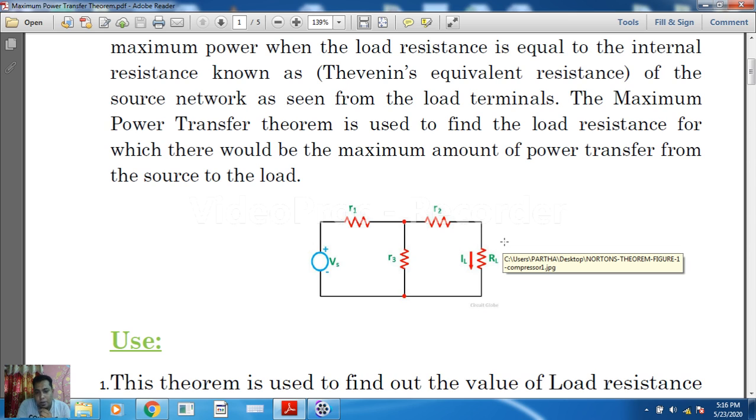In step 2, we made the circuit independent of source, any kind of source, maybe voltage, maybe current, and after that we viewed the circuit from the open terminal. So where is the open terminal? From where we have disconnected the load resistance. From there we have to find the equivalent resistance of the circuit. We have already done this.